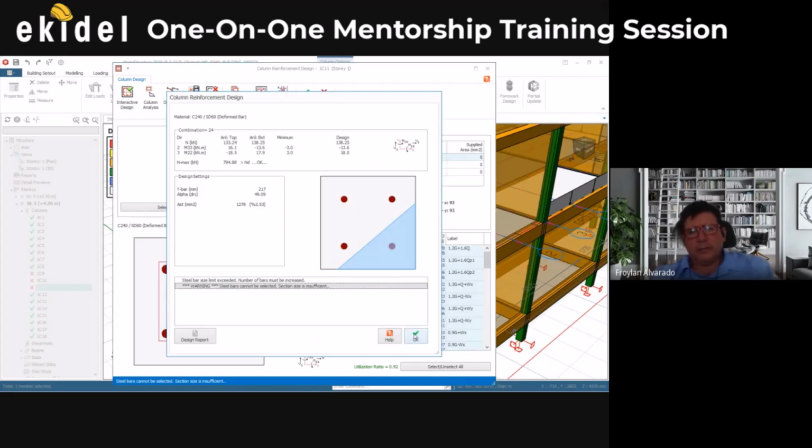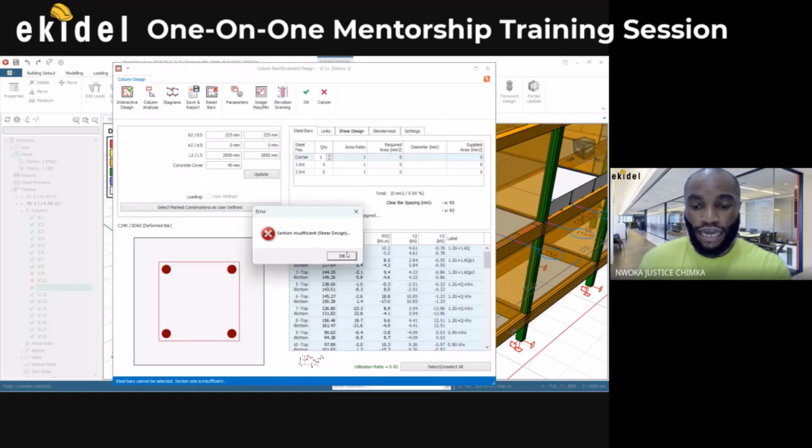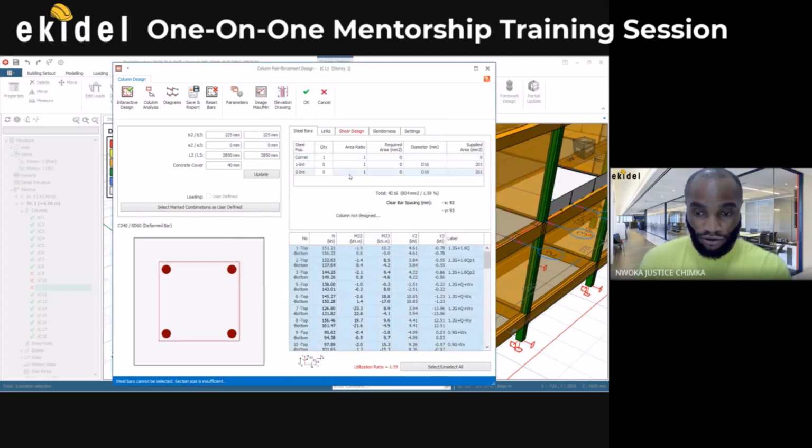Now watch: when I did a new design, you can see the warning that the section size must be increased. It's failing on shear design. So if it fails on shear, that means the section size needs to be increased.